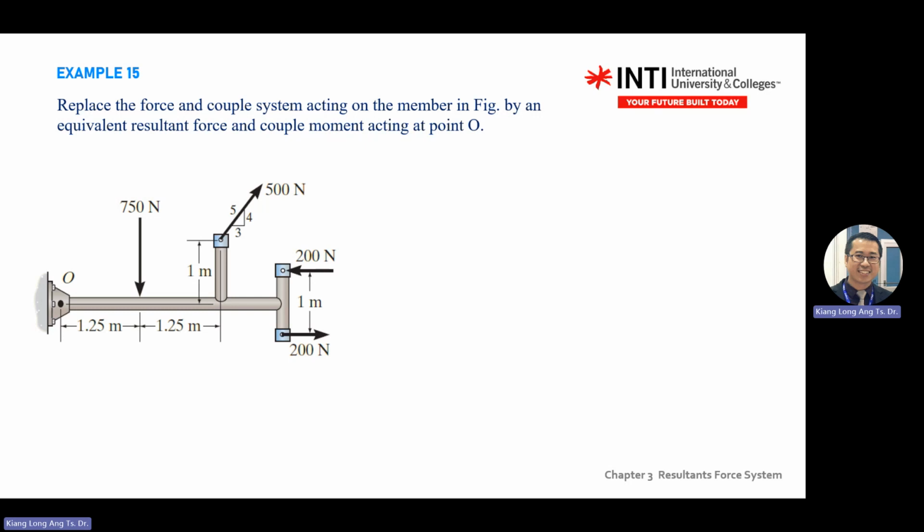So you draw a diagram, you transfer the whole object to a new slide of paper or new space. Copy all the dimensions. Copy the old location. Then the next one, you look at the forces. As long as forces have an angle, split them into X and Y direction. That is the first step. When you see forces, first step, split them into X, Y direction. After you split them, then you do the resultant forces steps, like what you learned in chapter 2.